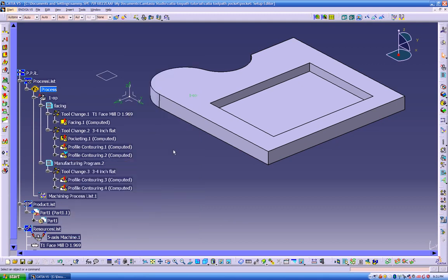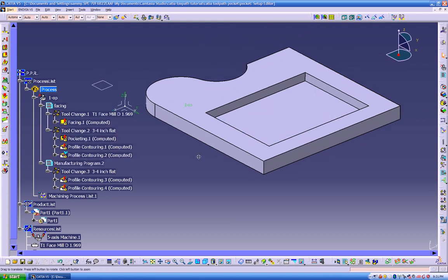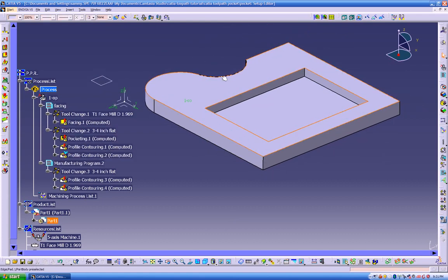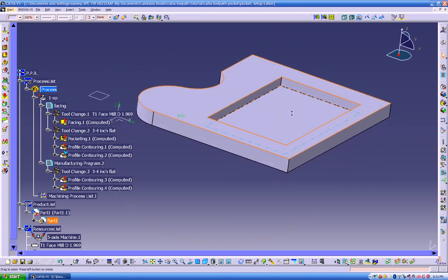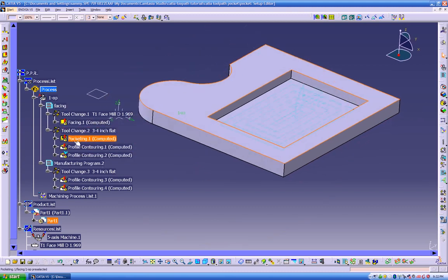Let's go lock them. Right now we can move this around without destroying our geometry. Now if I delete the cal part, just for the sample, my geometry is still gonna be intact because we locked them. We still can post it right now. We go outside, we post it, and our toolpath is gonna be over here.